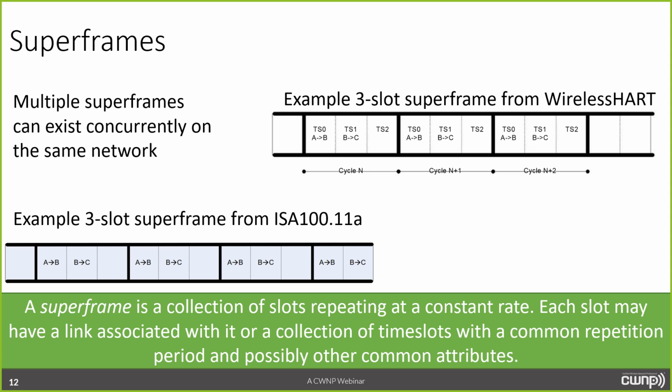Superframes are better thought of as windows of time, okay? But they are scheduled windows of time associated with a channel. So there's Superframe A for this time on channel 11, Superframe B for this time on channel 24. Okay, so superframes are boundaries of time. The frame is wrapping around a time boundary that contain slots. Okay, and those slots can be assigned to devices for them to communicate.